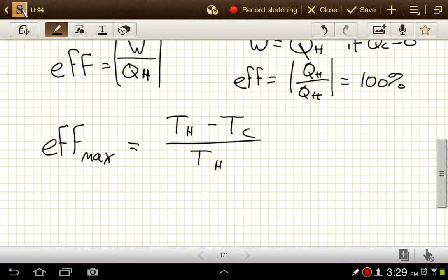But since our surroundings for these cars or whatever else we're talking about for engines is at some temperature above absolute 0, then even if we make really nice, slick, streamlined cars with well lubricated, almost frictionless, totally frictionless even engines, even in this idealized, perfect, impossible situation, we still can't get to an efficiency of 100% because we're not operating these in an environment that's at a temperature of absolute 0.